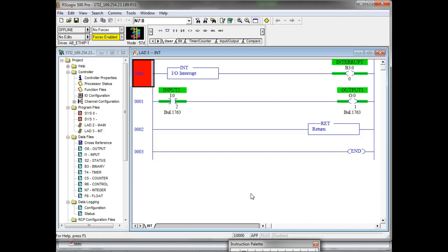So guys, what I'm telling you is that once you've learned a little bit of stuff, even though you go to work for somebody that has the 5000, and by the way, 5000 requires, they don't call them symbols, they call them what? Tags. They require tags. And also the 1200 requires tags. So from now on, guys, when you get into these more advanced PLCs, it's not optional. On the 500, the tags are optional. We call them symbols. These call it tags.